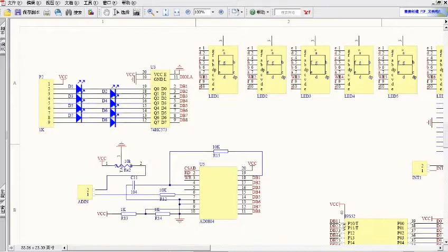And low normally means ground, which in the binary world we call 0. So if we want to make this circuit, we have to connect DB1 to ground. So VCC goes through the first resistor and through the LED diode and then connects with ground.